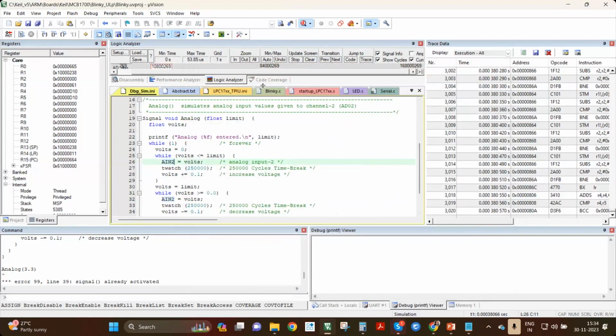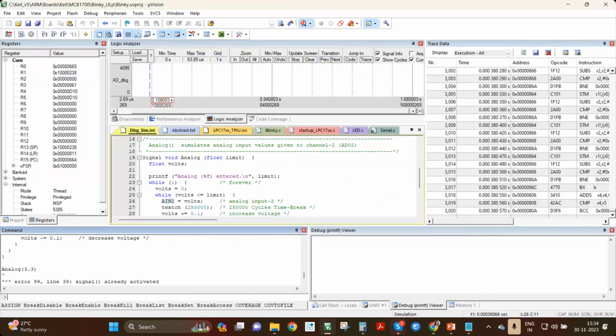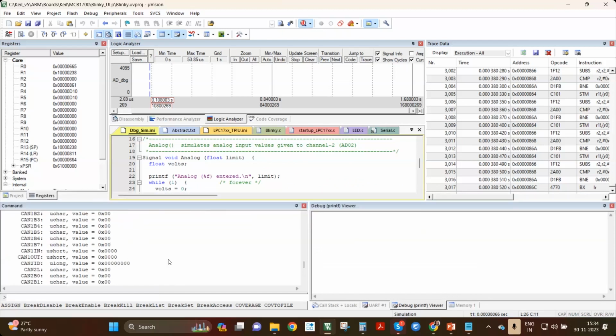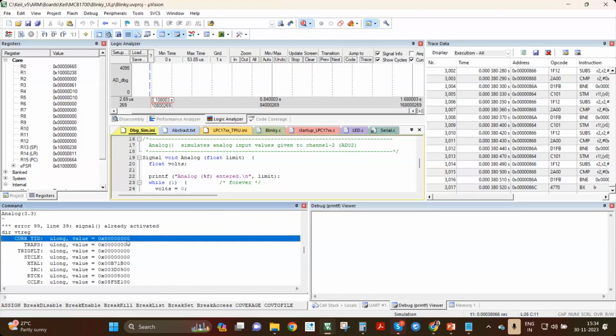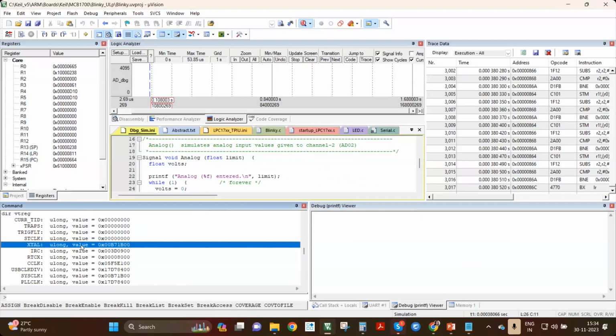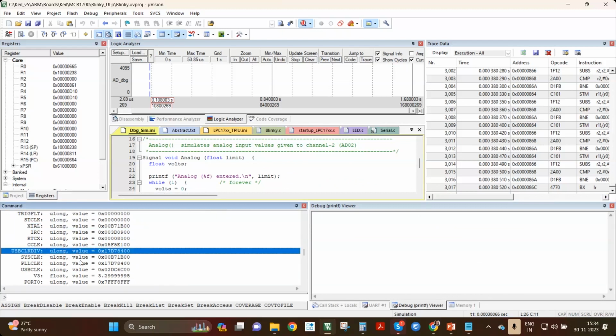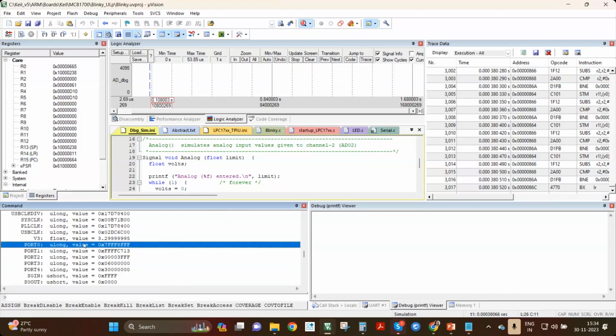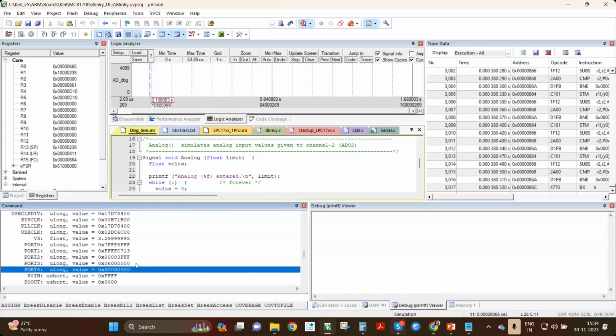Okay. Now we will see. Before that, I'll show you the directory of virtual registers. Here you can see these are all the virtual registers which are made available for the LPC1768 Cortex-M3 microcontroller. We have crystal, serial clock, USB. These are all for GPIO: port 0, port 1, port 2, port 3. These specifically give access to the port 0 pins, port 1 pins, port 2, port 3.